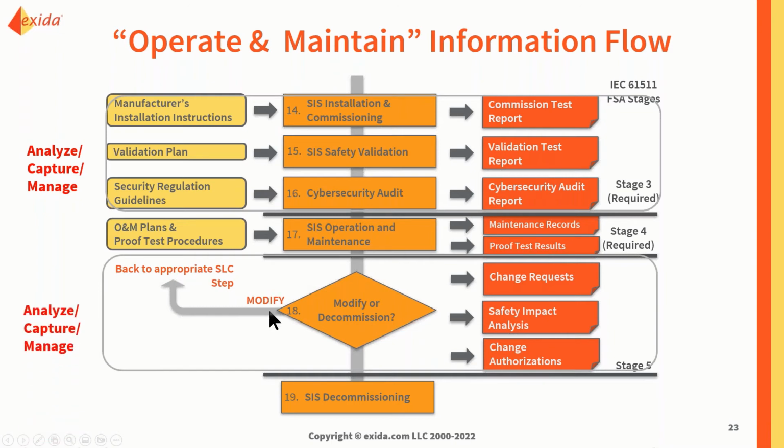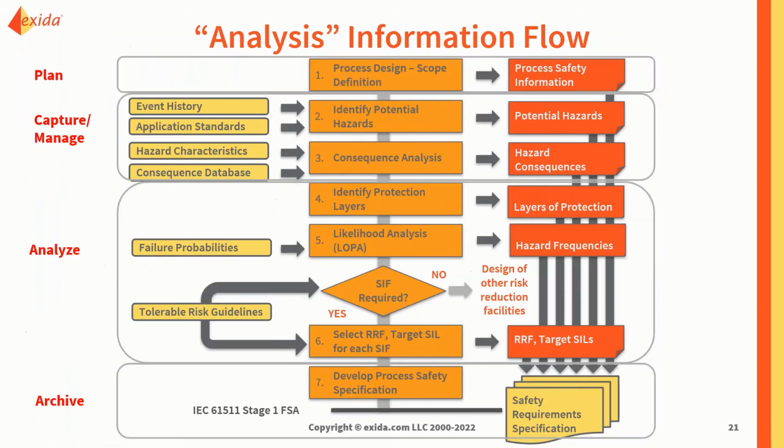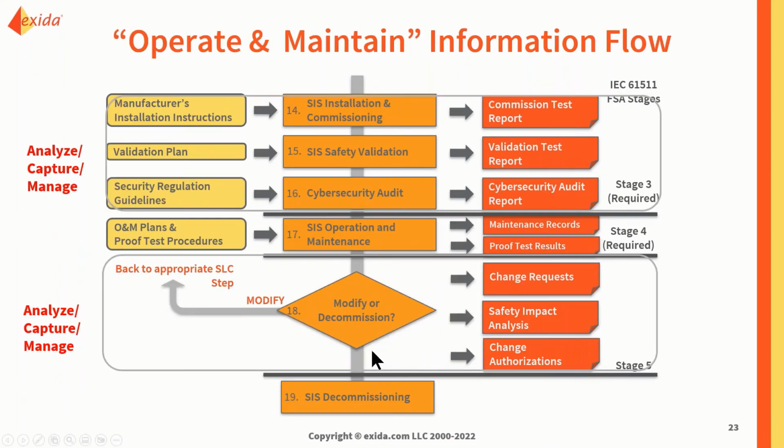Usually it's the same: analysis, capture, and manage. Usually it is going back to the analysis phase, where you have to do a new HAZOP or a new LOPA, and select a new SIL level for that particular SIF, because you realize that there are more safety incidents than you anticipated, maybe when you try to run the plant. So that would be related to those little bubbles within the data management lifecycle.